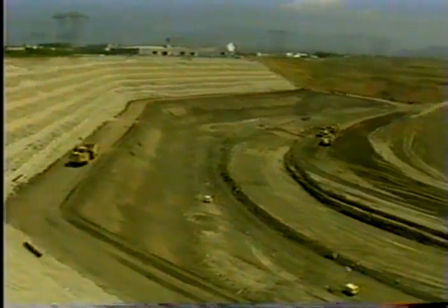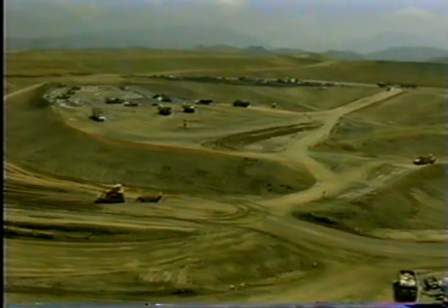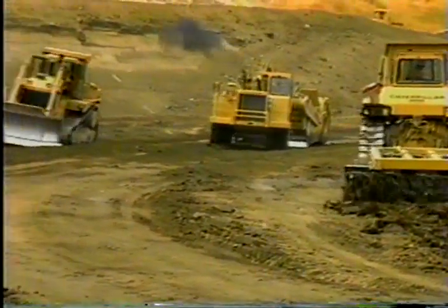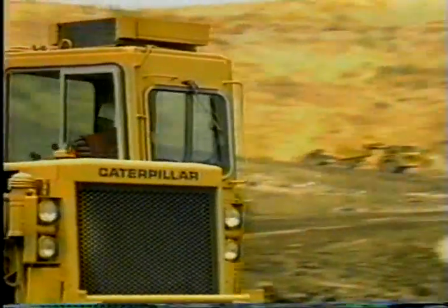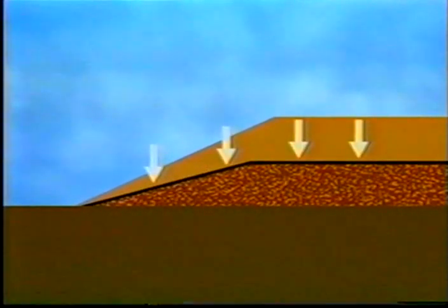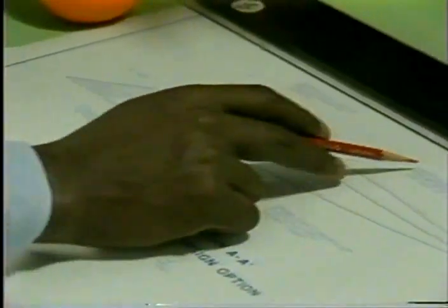New landfills are costly, take up valuable space, and involve often complex and lengthy permitting procedures. The reinforcing capabilities of geogrids and geotextiles have now made it possible to extend existing landfills outwards and upwards. This is an example of a piggyback expansion where a new landfill was constructed on top of an old one. The reinforcement had to ensure that the weight of the new waste above did not cause differential settlement as the waste in the original landfill compressed. Designing a piggyback expansion is extremely complex and requires specialized skills.